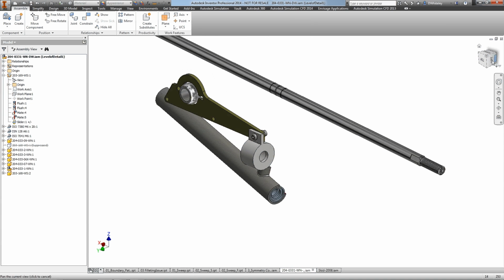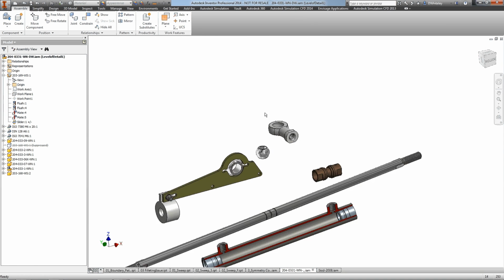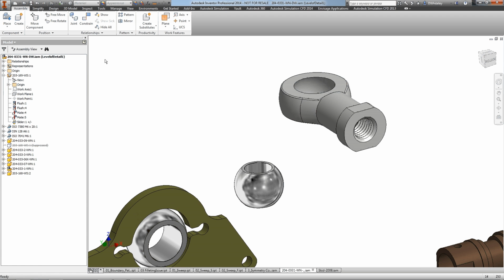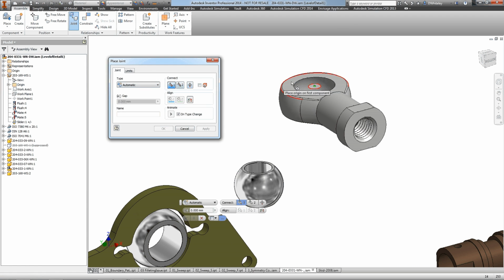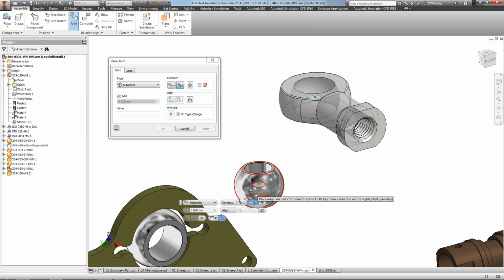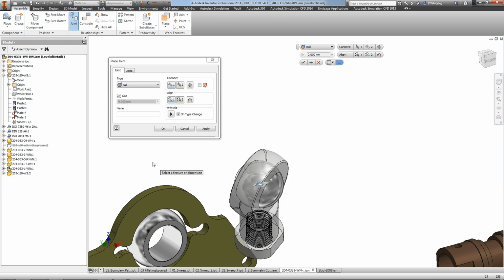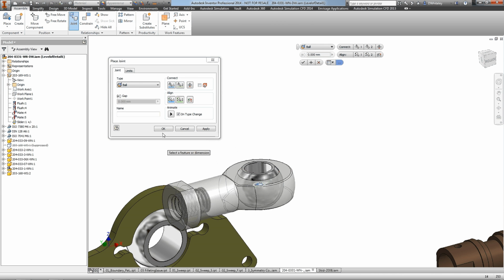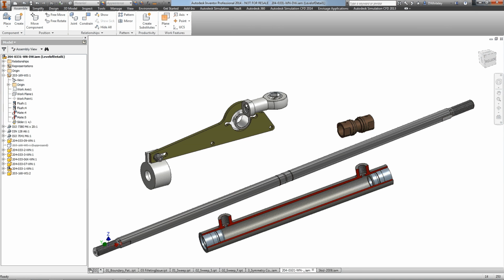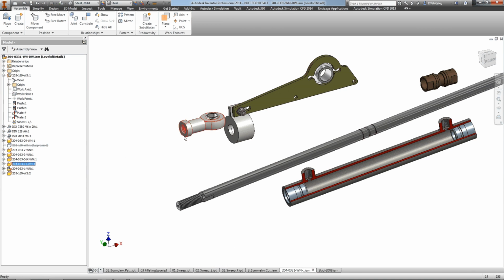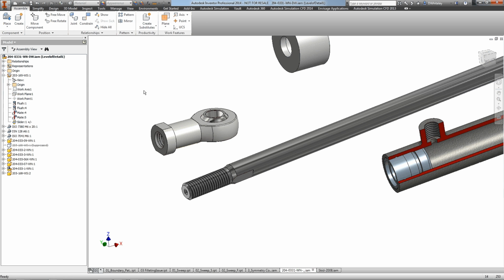If I just continue on a little bit further, I won't assemble all of this, but if I take this ball joint here, again go to the joint command, select the sphere, you'll notice that there are 3 options. You need to be careful you select the mid point and not the top or bottom points here, and likewise with the ball joint there, that will put the 2 together. Show a little video of how it's actually going to move this joint.